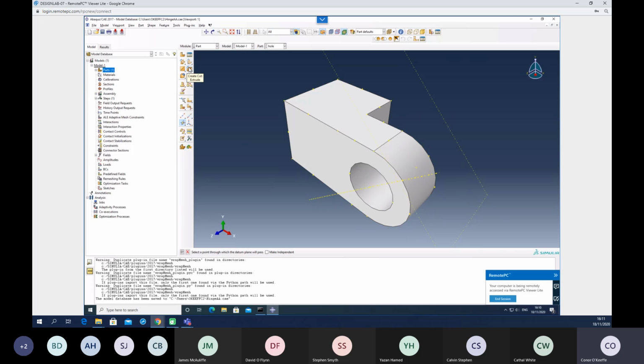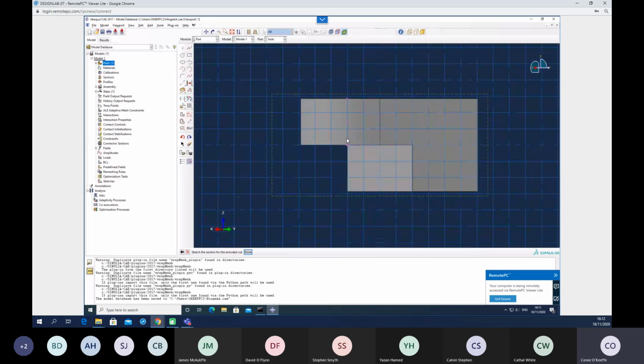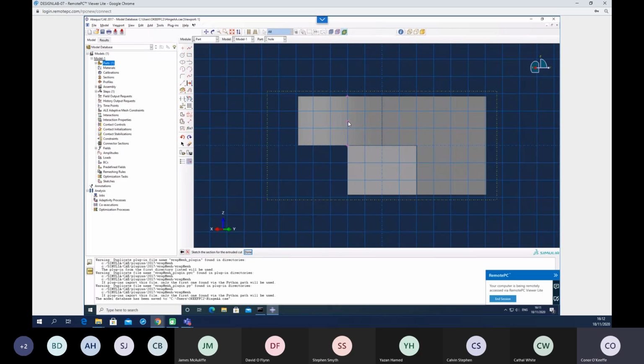So previously, to add this flange, we used create solid extrude. So the opposite is create cut extrude. So we use this tool, create the sketch plane. Click on the sketch plane, which is this vertical on the right here. Okay, so now we can sketch here, and we can use this point as our center point.